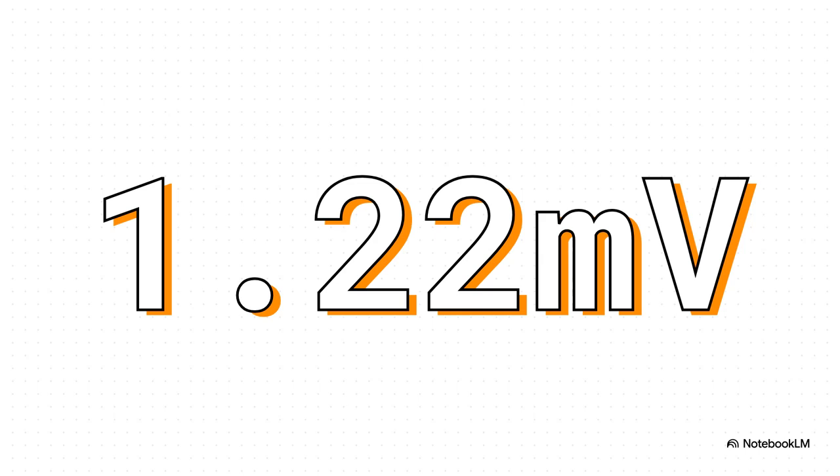And believe me, this detail matters a lot. A really basic system might only be able to see temperature changes in whole degrees, but a system with higher resolution can see changes of a tenth or maybe even a hundredth of a degree. To put some real numbers on it, just moving from a standard 8-bit to a 12-bit system gives you 16 times more detail. That is a massive leap in sensitivity that allows for way smarter, finer control.